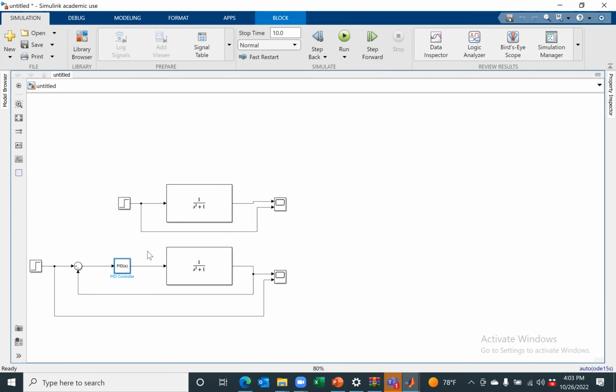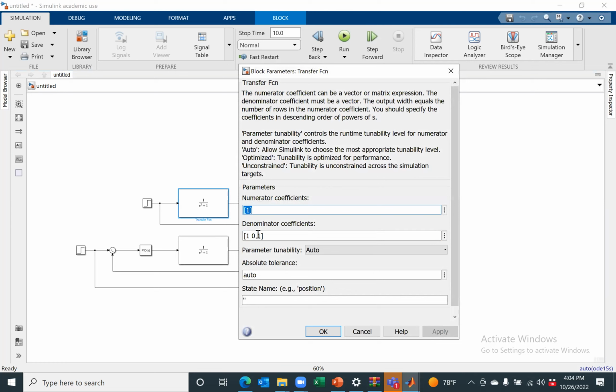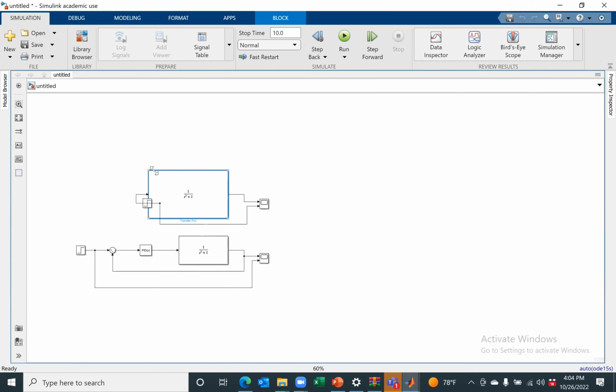Yeah. For the transfer function blocks, is it necessary for the transfer function to actually show? Because once I start editing it, it is going to apply numerator, denominator. Yeah, just this numerator and denominator. So for example, if you add some more terms here, then it will be different. Okay, so it won't show the numbers. That's fine. Try expanding. In older MATLAB, it used to show num versus den, but in newer MATLAB versions, if you expand, it may show the transfer function.